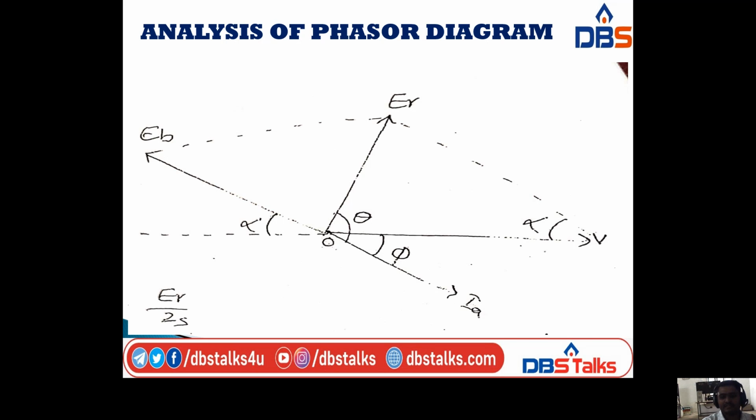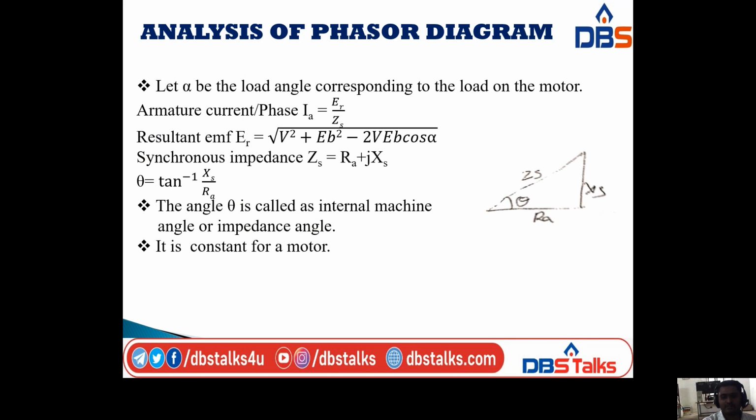Let alpha be the load angle corresponding to the load on the motor. At that time the armature current per phase is Ia equal to ER by Zs, and the resultant EMF ER is equal to root of V square plus Eb square minus 2 V Eb cos alpha.